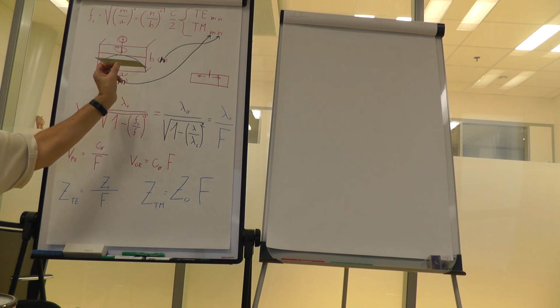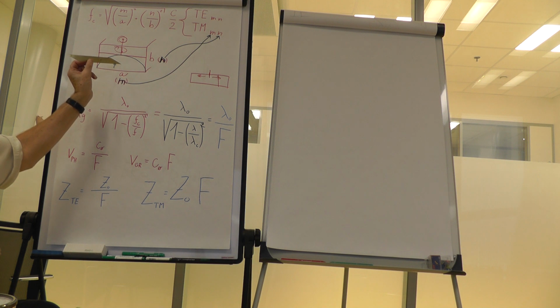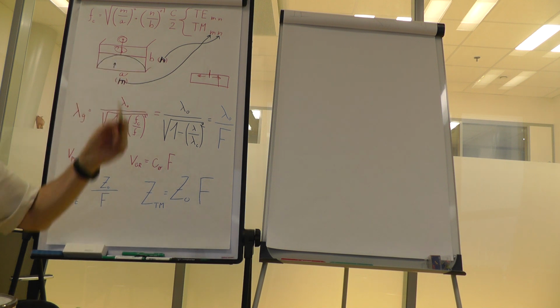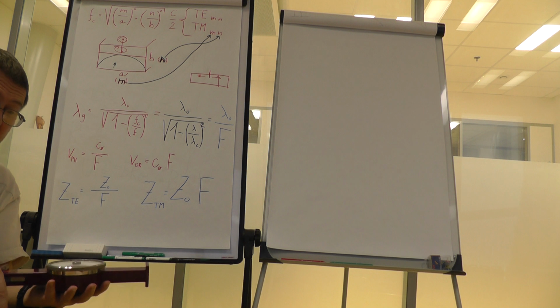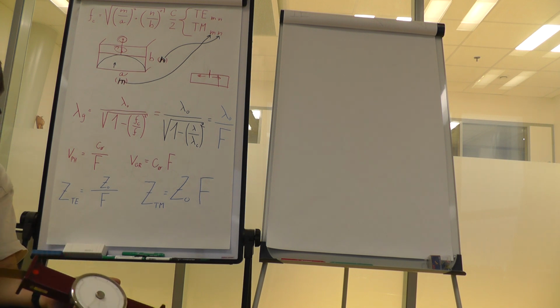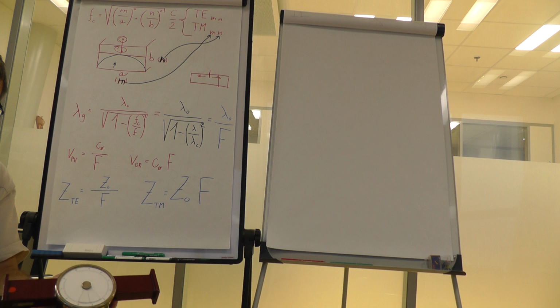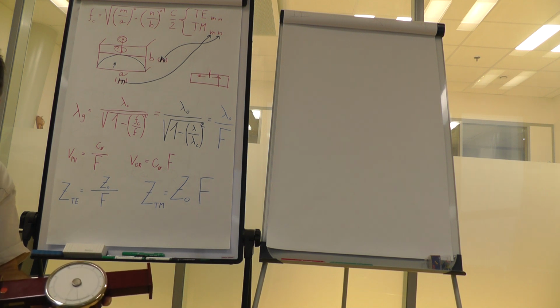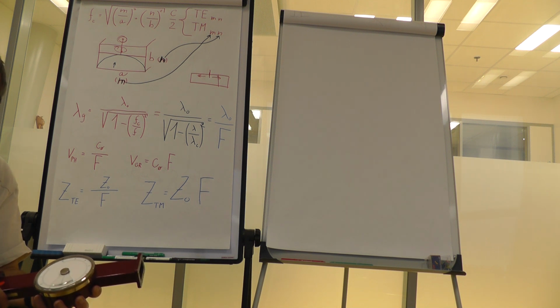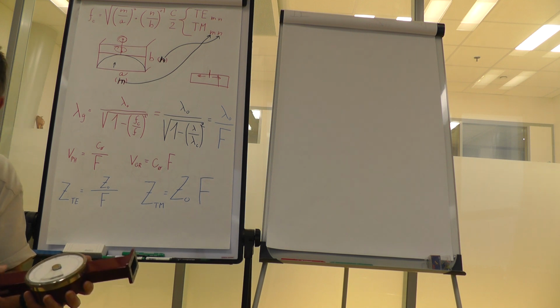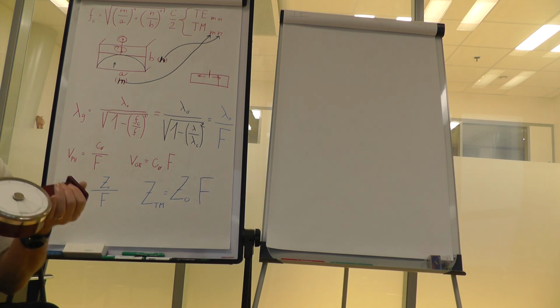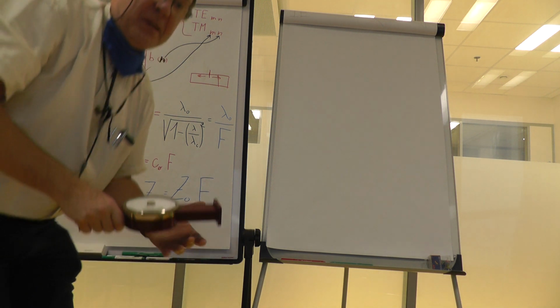So increasing the interaction would slow down the wave, and as we have a precise screw manipulating it inside, we can handle the phase of the signal by setting the distance in the waveguide. That's something that's used to handle magnitude as a variable attenuator or phase as a variable phase shifter, and the arrangement could be like the one I have described now.